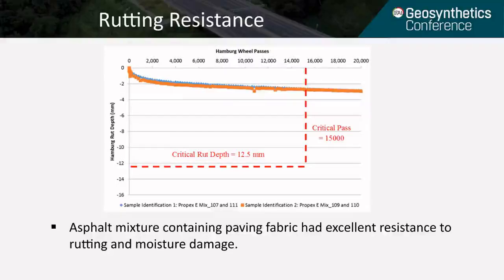In addition, from these rutting curves, we did not see any inflection point, or what we call stripping point. This indicates the material has no moisture damage issue.